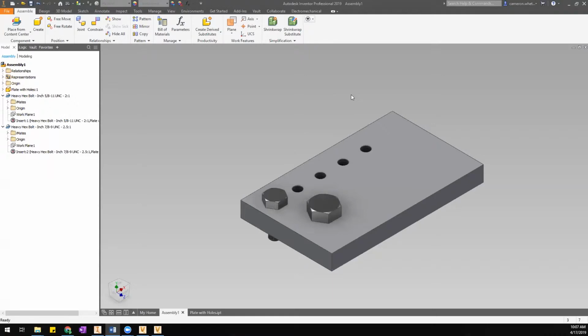These Content Center editors, you really do need to restrict the actual editing permissions for the Content Center. If you're using Vault, the way you would do that is there's actually a specific role set up in Vault for Content Center Editor. Anyone who doesn't have that specific role basically can't do any kind of modification to Content Center at all. They can use it all day long, but they can't modify a single thing. So Vault is nice in that it handles Content Center editing permissions.